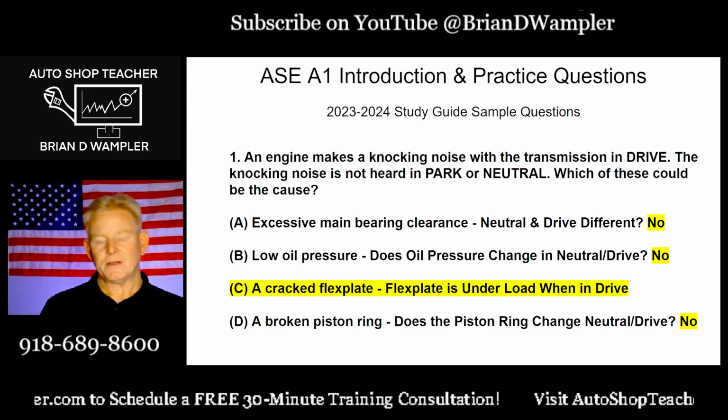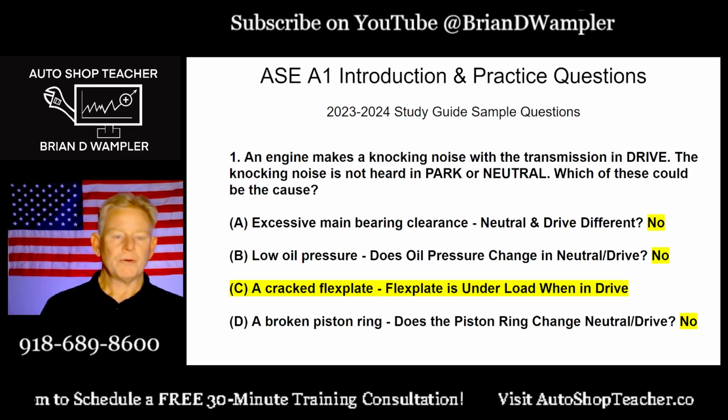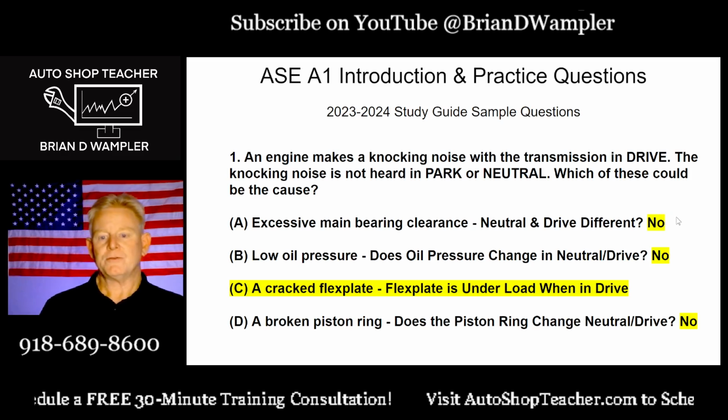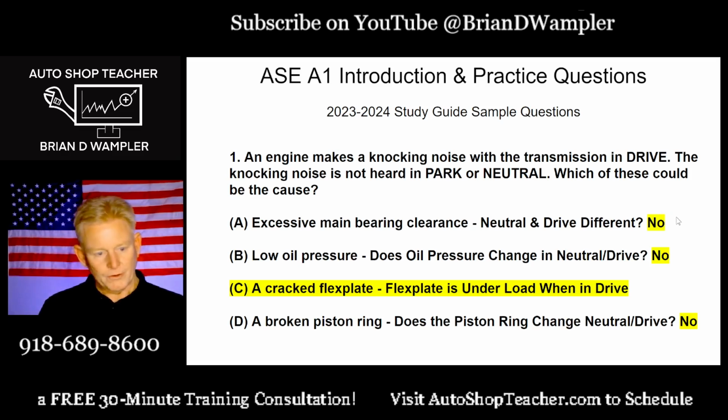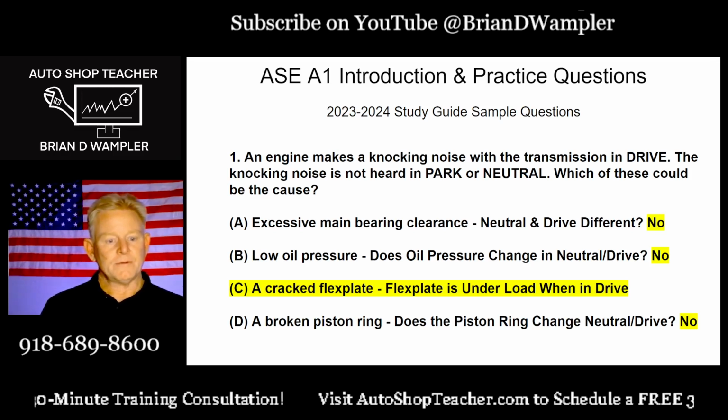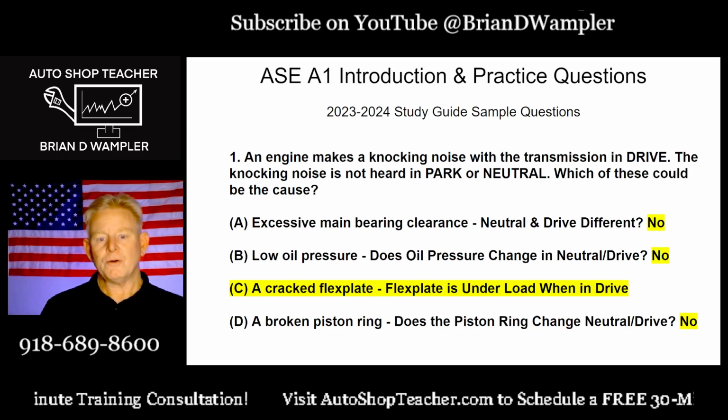The piston ring, the condition of it, say if it's broken, it's not going to suddenly unbreak or quit making noise just because you've put it into drive. So the correct answer for this one is a cracked flex plate. The flex plate is put under load when in drive.